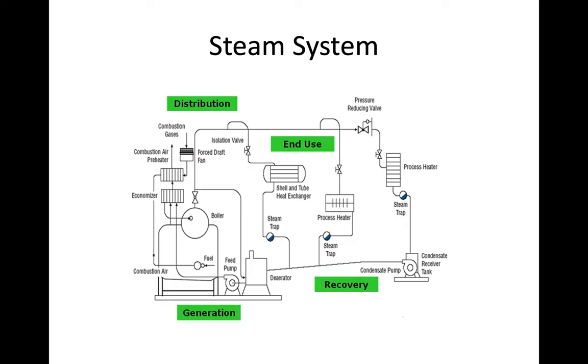You just control the pressure of steam, and from that, you can also control the temperature and other parameters such as fuel flow rate and combustion air flow rate.